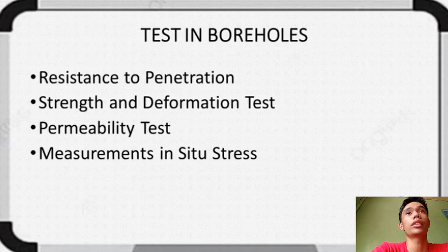In the test in boreholes, there are many tests conducted in boreholes, described here under 4 headings. The first heading is those that measure the resistance to penetration through the base of a borehole, or the resistance to penetration; the man-made force required to deform the hole, the strength or deformation test; the amount of fluid that can be passed to and from a hole, or the permeability test; and lastly, the natural forces that deform a hole, or the measurement of in situ stress.